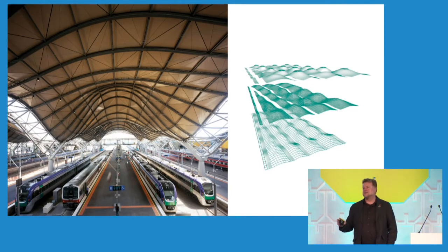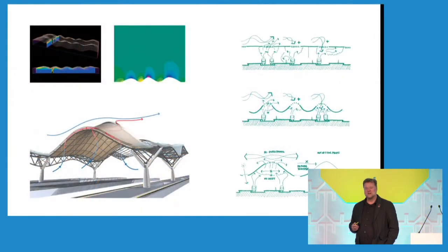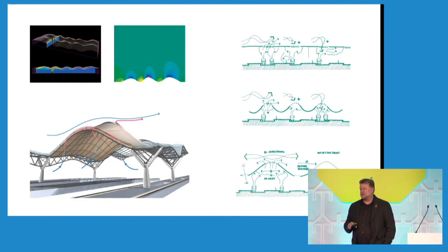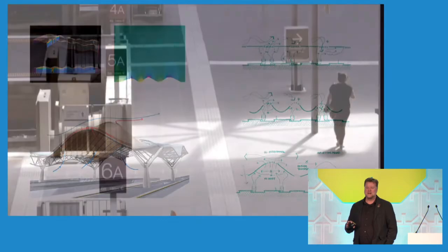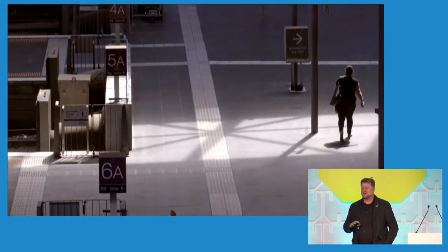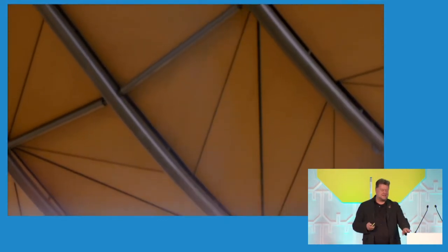there's prevailing winds, that if we designed the roof almost as a series of moguls, it could actually help extract the air from inside the building and also keep the building cool. So actually, the geometry of the roof is the entire building environmental system. So what we did was actually create a completely net zero system. So the roof shape itself provides the entire environmental tempering of the space inside.